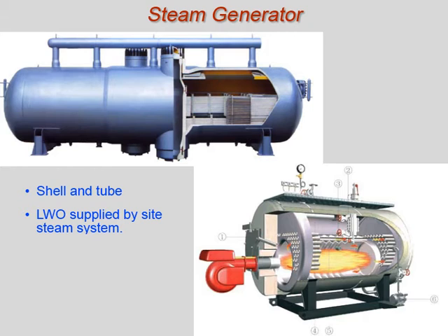The feed pumps continuously supply the shell of the steam generator with feed water through the feed water inlet. As the feed water flows around the outside of the tubes, the steam inside the tubes gives up heat to the feed water. There is sufficient energy in the high-pressure steam to boil the low-pressure feed water.